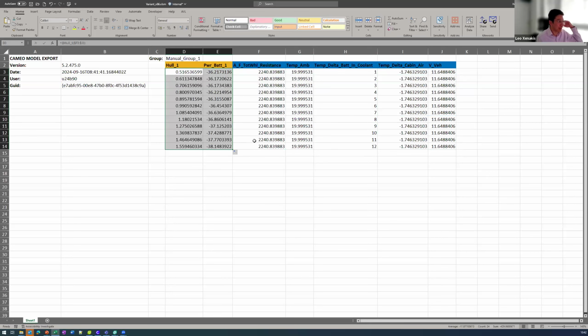So yeah, if you put in the cycle data here, for example, you can immediately just simulate the whole cycle, even in Excel. And you can see here, for example, that you're well within the hull. These outputs here of the power can be trusted. As you're starting to approach the edge of the model, it becomes less sure about the output. Now here, I wouldn't really trust the output at these conditions.